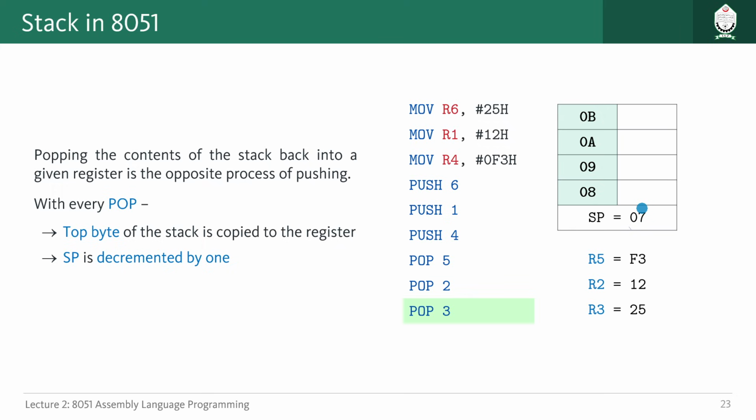Whenever you push, the pile gets up and we have higher addresses, SP gets increased, and after each pop the topmost value gets stored onto a specific register. In this way, one by one, the pile gets reduced, the stack gets reduced. Okay,